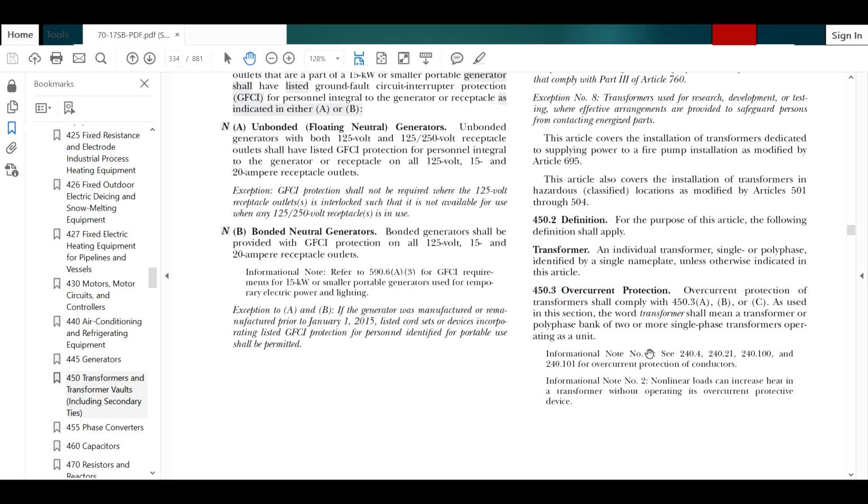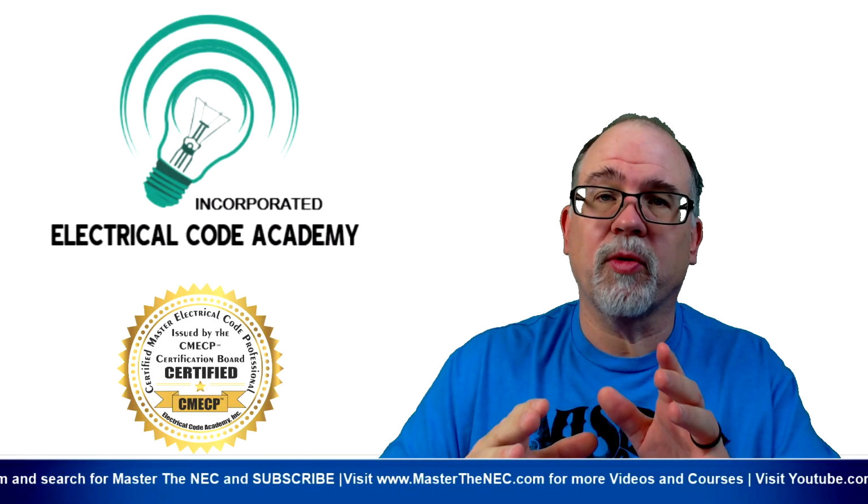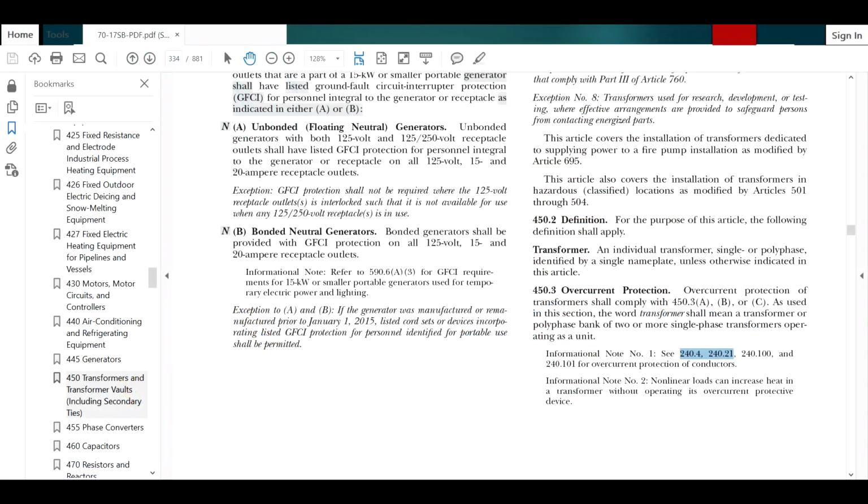There is an informational note that reminds you that 240.4, 240.21, all of those things have to do with conductors. We have to remember that those conductors have to be protected at their ampacity unless some kind of tap rule or secondary conductor rule applies, and then we will apply it. Other than that, the protection we're talking about here in 450.3 is simply to protect the transformer. That's all we're doing here. We're going to keep it light and simple as we build on this knowledge. When we're back in the code, we're going to see that it deals with 450.3(A), (B), and (C).